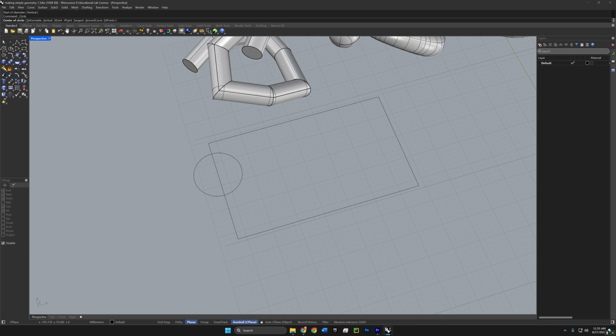So let's click on the circle button here, and let's select the 2-point option so that we can set its diameter instead of its radius. And I'll hold the Alt key in order to temporarily turn my OSnaps on. And let's turn off the point snap and the center snap and the end snap too, so that we're just left with the near snap and the intersect snaps being on. And then we'll click here at the intersection and we'll come down to about here.